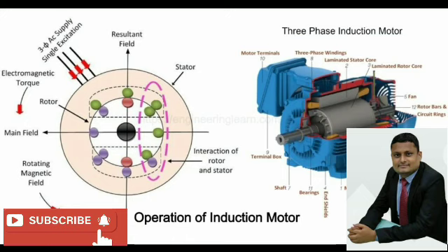Some disadvantages are also there, so note them down. Disadvantages are increased cost and weight of the copper coils. Teeth thickness will get reduced, which means teeth remain mechanically weak, with more core losses and more magnetizing current.